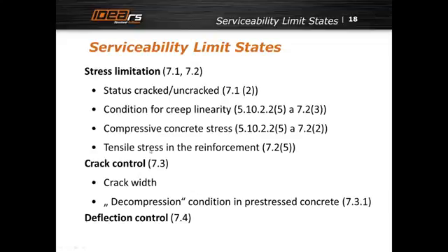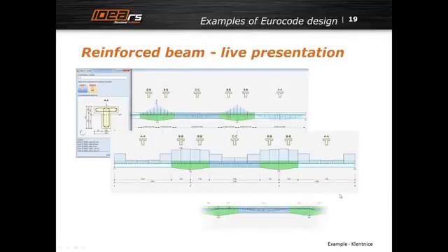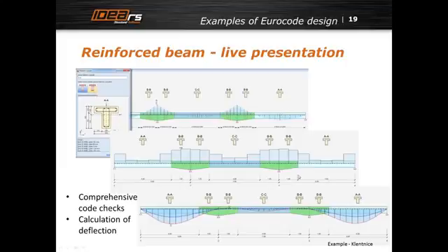Also other checks are done in the program, including crack width and so-called decompression, which is again a little bit confusing with the method of decompression stress and decompression force. There's nothing common. This is only the condition of compression reserve, which is required in the case of certain exposure classes. I will show later. Of course, deflection control.